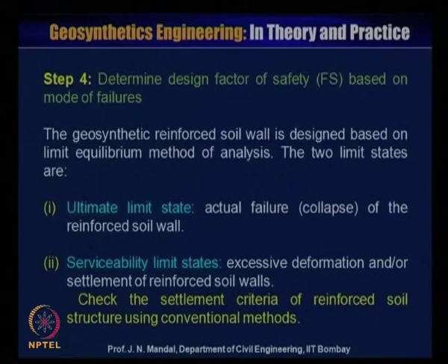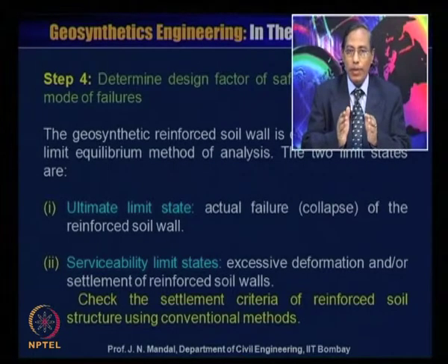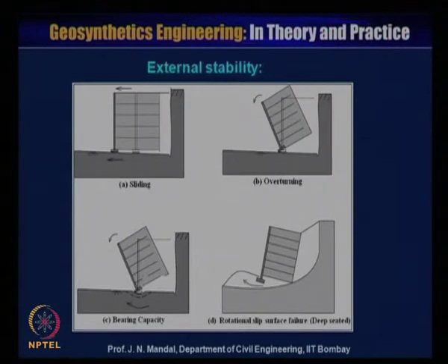The two limit states are: one, ultimate limit state, actual failure or collapse of the reinforced soil wall, and two, serviceability limit state, that means excessive deformation and or settlement of the reinforced soil wall. You have to check the settlement criteria for reinforced soil structure using the conventional method. Now we will discuss the external stability.